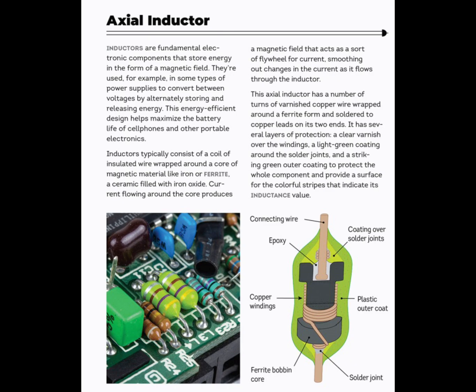They are utilized in applications like DC converters where energy storage is required. They are used in tuning circuits in high-frequency applications for tuning and impedance matching. For using this, always check the current rating to avoid saturation or overheating. Ensure that the inductance value is appropriate for the intended application. Consider the operating temperature range specified by the manufacturer.